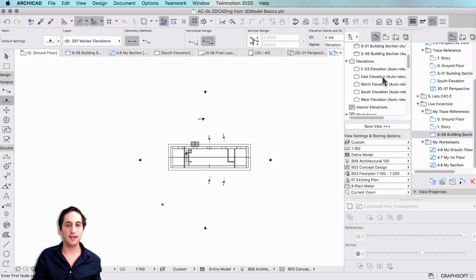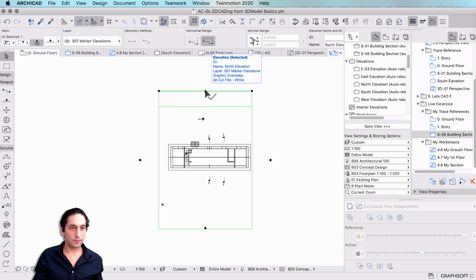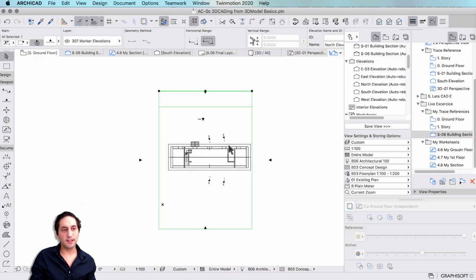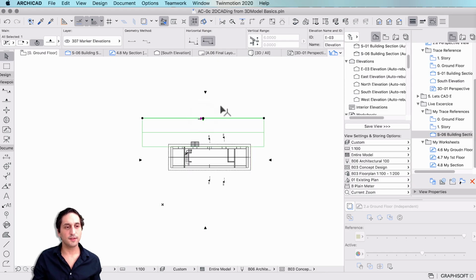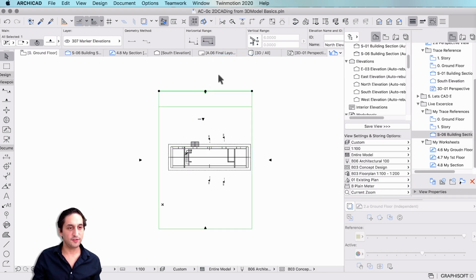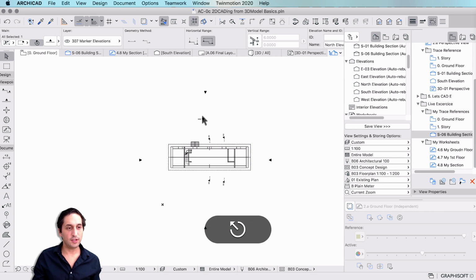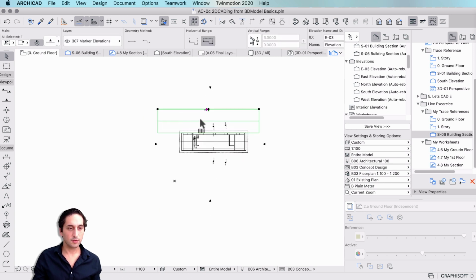Okay, I think in our case we used the north elevation automatically. We just moved it around. That also works. But here it's important that if you do generate it, notice the difference of these 2 lines. It needs to be readable what we're doing here. So for that, you need to select it, and these 2 lines, you need to push them behind the house, both of them. I'll explain more about them.